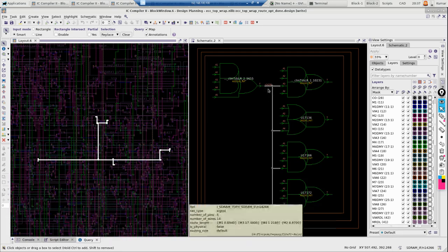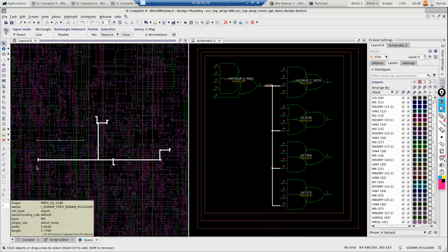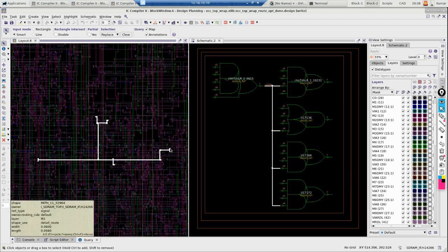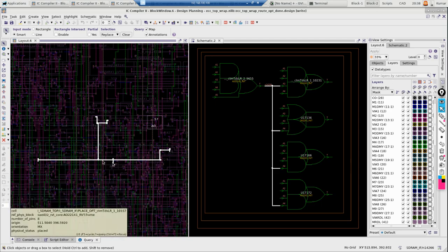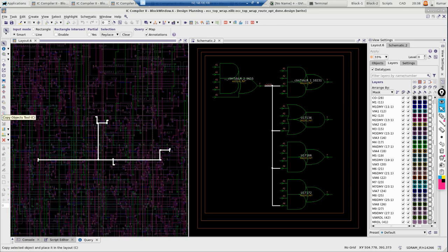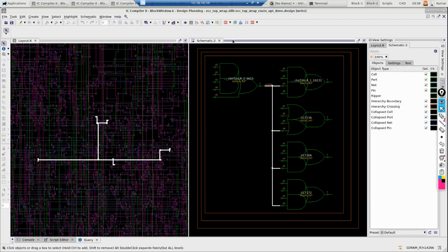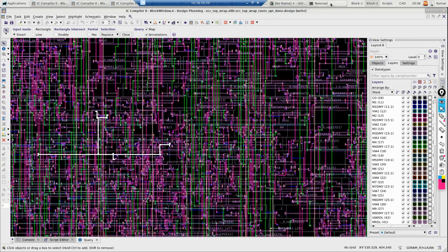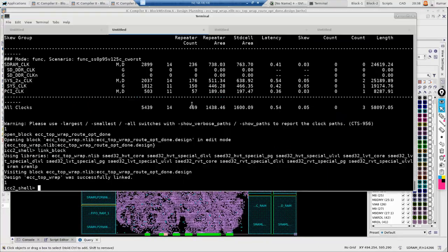Logically, it's one cell driving one, two, three, four different fan outs. You see here, one, two, three, four. All of them are routed using the layers. Okay, this is something that we call a route. Now, after route, what do we check? As I told you, we would check for zero opens and shorts.